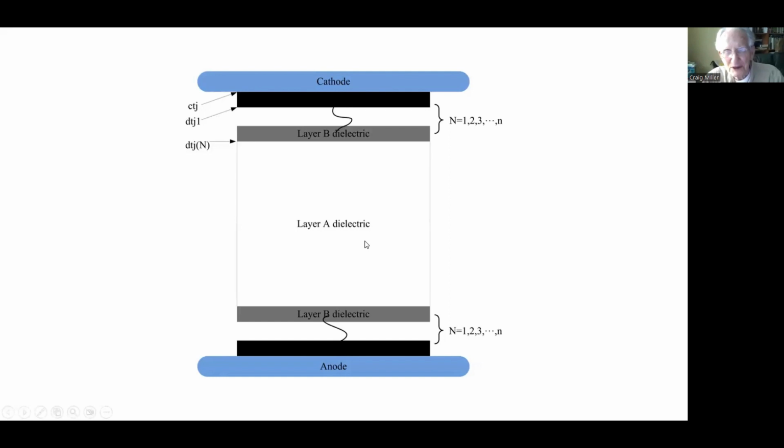Because this is known, some workers tested putting a layer of insulator material with a relative permittivity higher than that of the main dielectric between the cathode and anode, and then perhaps more layers, each with a higher dielectric constant, with the one closest to the electrodes having the highest.